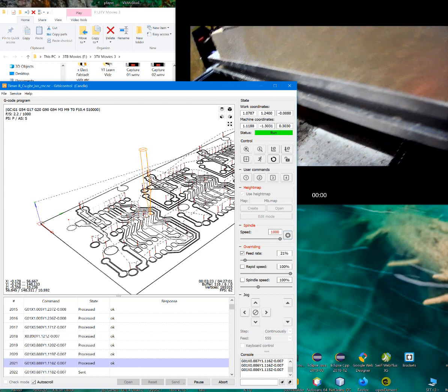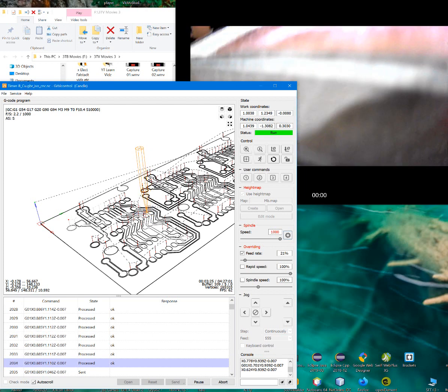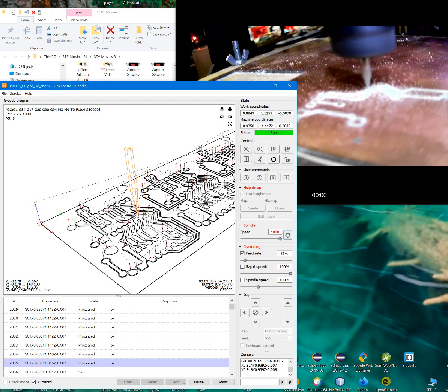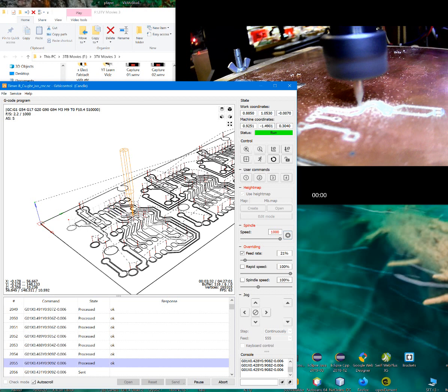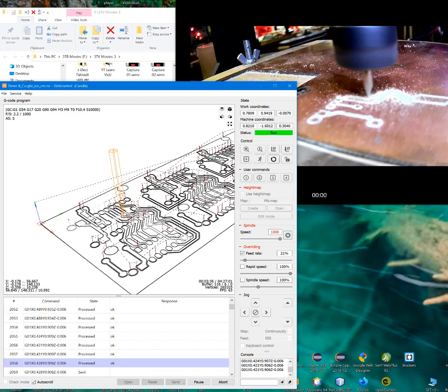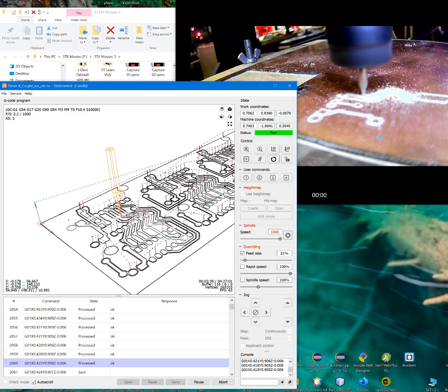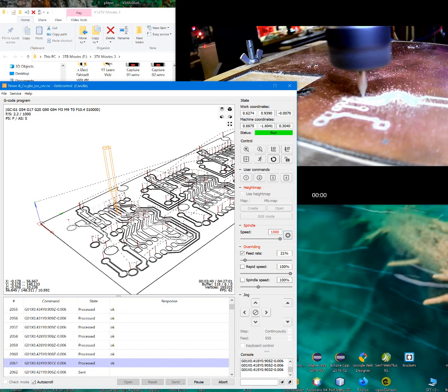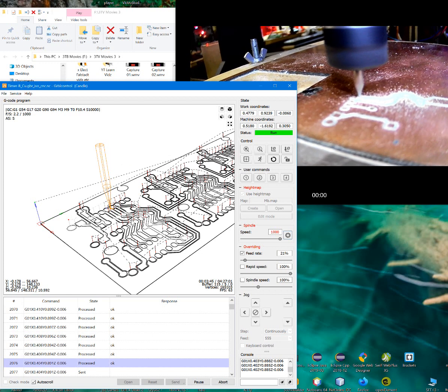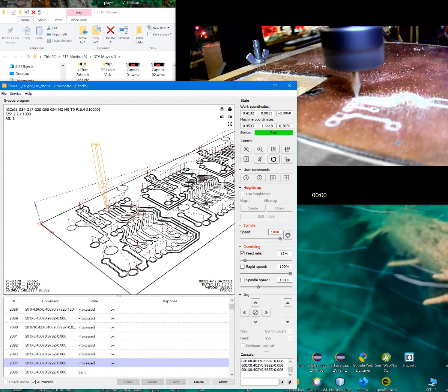Take a look at it. Yeah, that still could be wider, but it's at least wider than it was before. That's certainly way narrower than 25 mil, so in theory I had to stop it and restart it just to be safe, because it's still eating up a little too much out of my trace width.